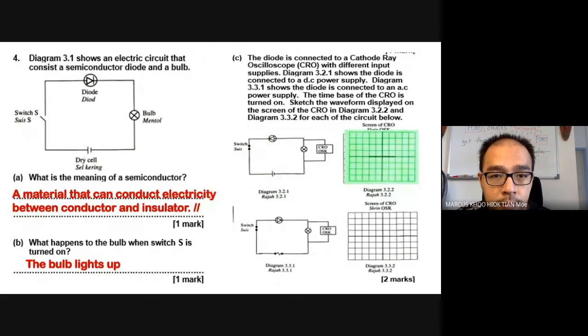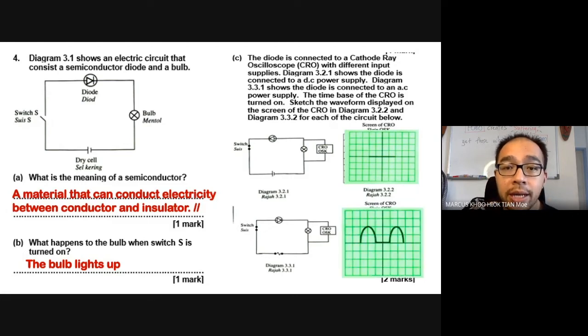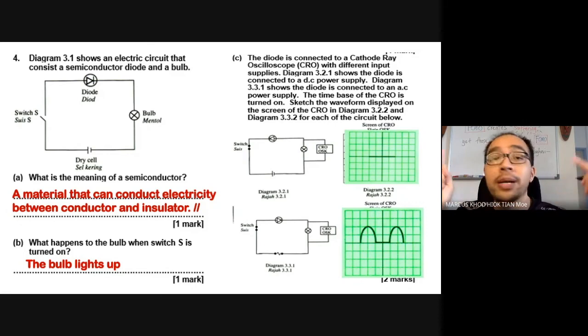Now, in an alternating current, we know, because this is a half-wave rectification circuit, you're going to get on, off, on, off, on, off, on, off. Pretty simple, actually, not that difficult. We just have to know reverse bias or forward bias. That's it. Is it reverse bias? Is it forward bias? Forward bias, current flows. Reverse bias, current doesn't flow.